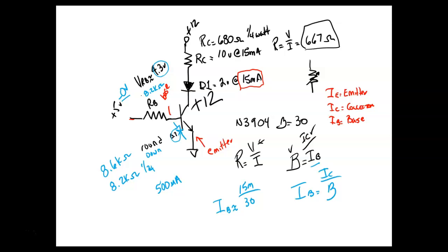So that's why the total voltage is dropped across an open element in a series circuit. It's not because current flows through it, right? You understand? It's just that nothing else in the circuit is dropping any voltage. So if I go over here to this light switch and I open it up, I'm going to measure 120 volts across the switch because these guys up here are not dropping any voltage. So that's why you measure the total voltage across an open element in a series circuit. Helps us find opens, really. Resistors burn open, helps us find wrong fuses, really.